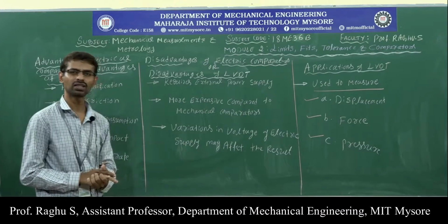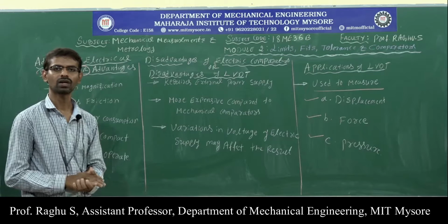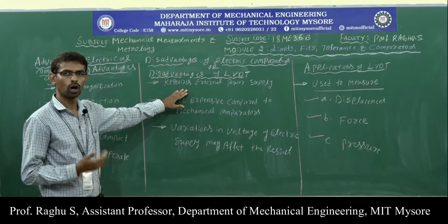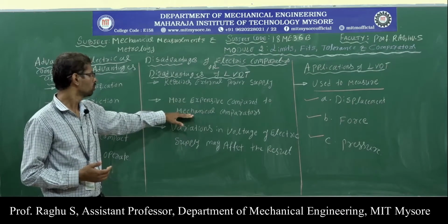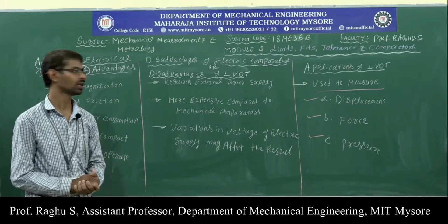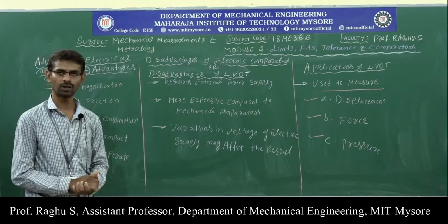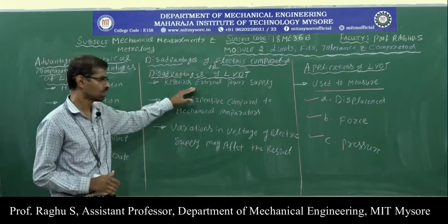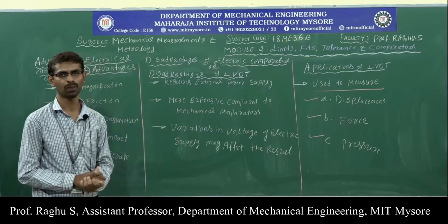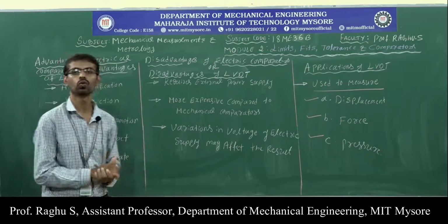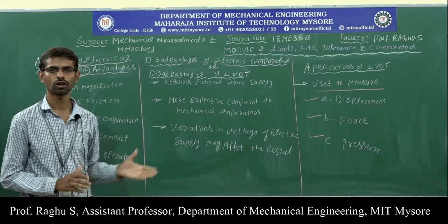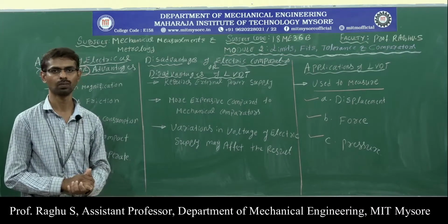Then coming to disadvantages of the electrical comparator or disadvantages of LVDT, it requires an external power supply to operate. Next, it is more expensive compared to mechanical comparators. Then variations or fluctuations in voltage may affect the result. So these are a few disadvantages associated with electrical comparators.